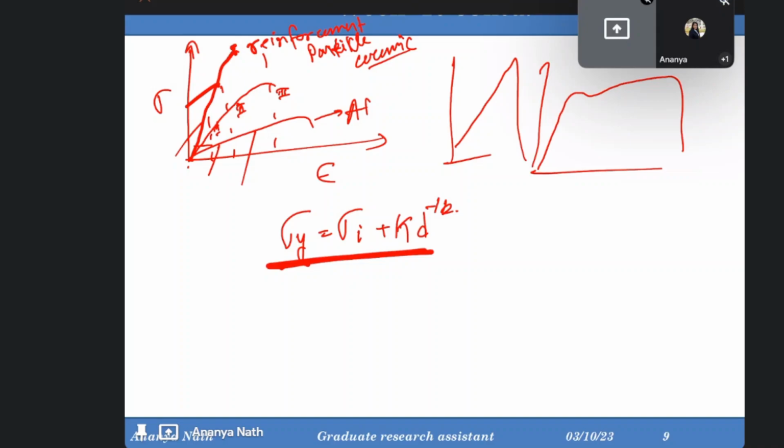But again, it was not mentioned, but I have gone through some literature. It has been found that when you mix micron level ceramics into the aluminum alloy, you'll find a good strength. But when you go for nano ceramic powders, you'll have ductility, means the strength will decrease.